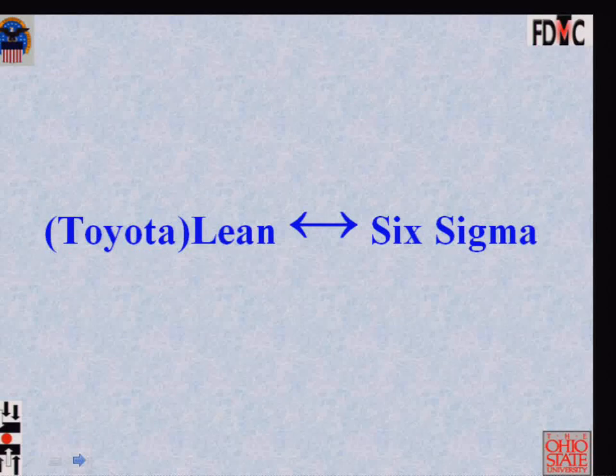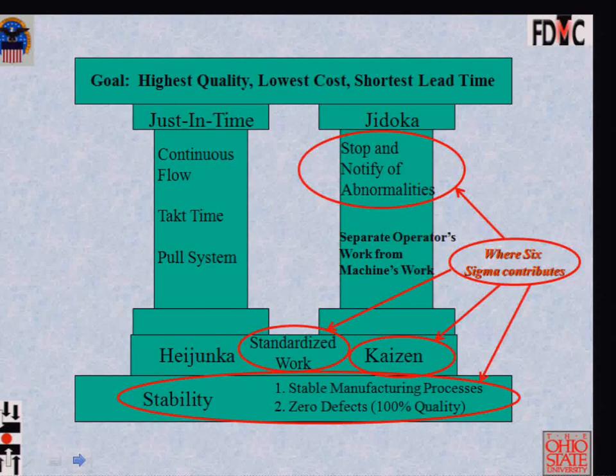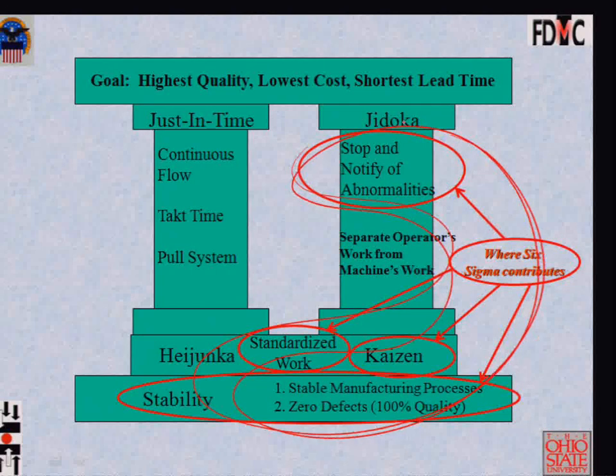So again, I just want to put in a slide on what's the relationship between Lean and Six Sigma? Like I said before, I think that Six Sigma is already kind of captured in these components of the Toyota production system. If you read Shigeo Shingo's Quality at Source, Zero Defects book, he kind of points out that you shouldn't get too taken up with statistical data analysis. Focus on the people, the equipment, the methods, and the materials, the classic Ishikawa diagram components. And he feels that so much of the process and product design and people's training is important to ensure good quality, and not that you can put analysis and inspection to get quality of the product.